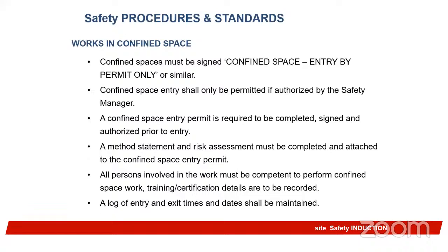All persons involved in the work must be competent to perform confined space work. Training certification details are to be recorded. A log of entry and exit times and dates shall be maintained. If you want to carry out a permit, there are things that you should look out for. There must be air testing to test the components of the chemicals or the air present inside the confined space to make sure that it is habitable for someone to go into.